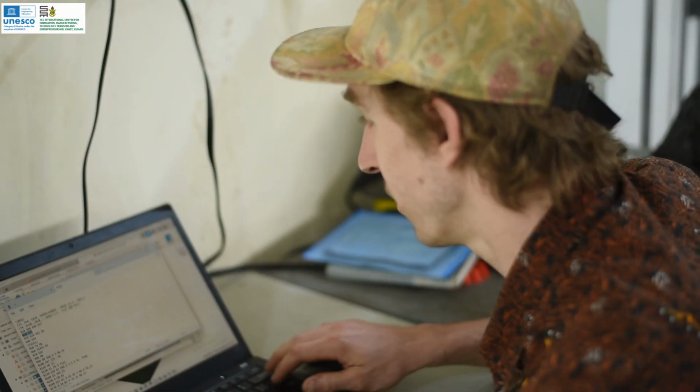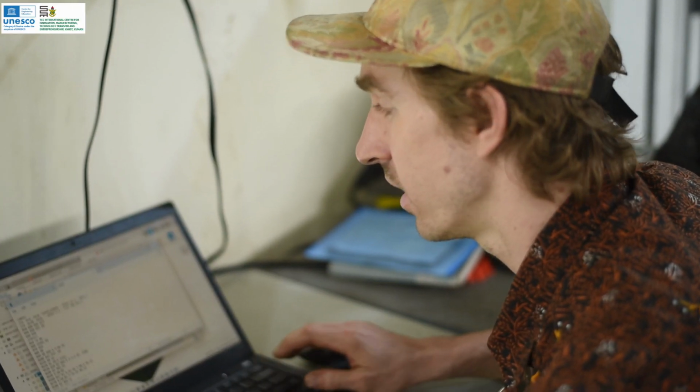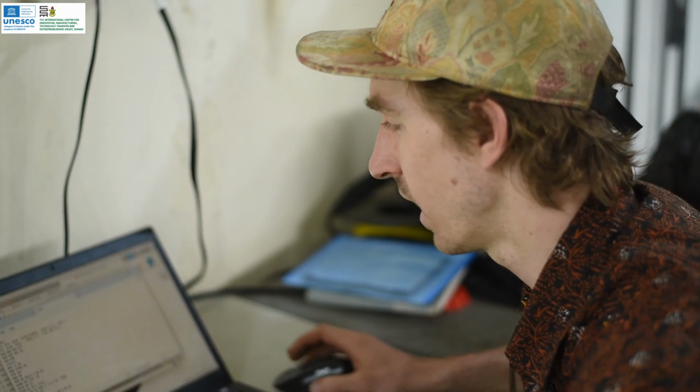We finally figured out what those are. First of all, the G20 or G21 command, typically that's used to switch between metric or imperial units. The GSK controller doesn't want you to tell it which units to use. You've set that already. It doesn't want to hear it again. It will not take a G20 or G21 command, so it has to be deleted out.